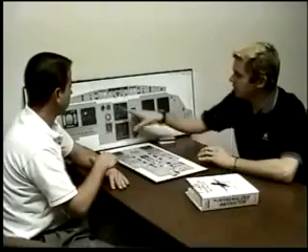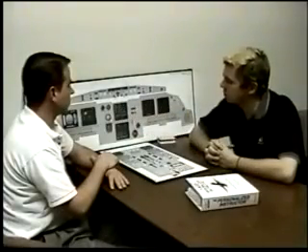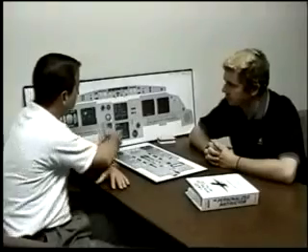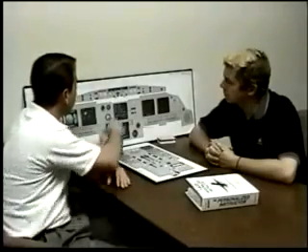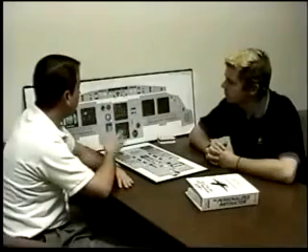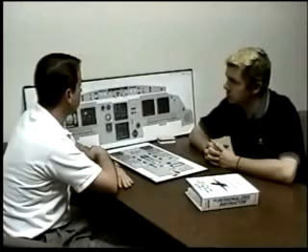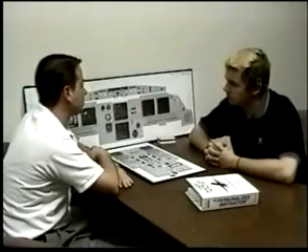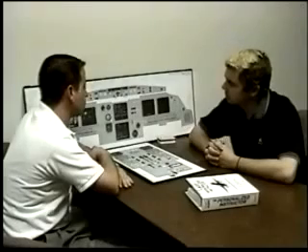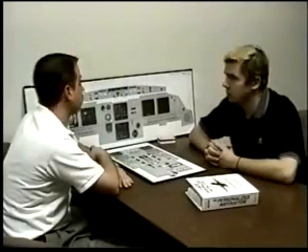Well, I'm going to look on the engine page and look to see that the two top indicators go from amber X's to their normal indication. Anything on the lower display? The engine page will then show up. Now that your EPR and EGT have gone from amber X's to the normal display, what's being powered now? The FADEC power. Okay. Normally, what powers FADEC? The FADEC has its own alternators.